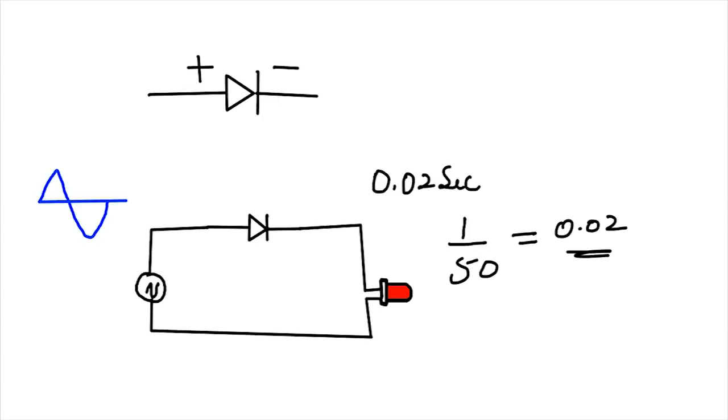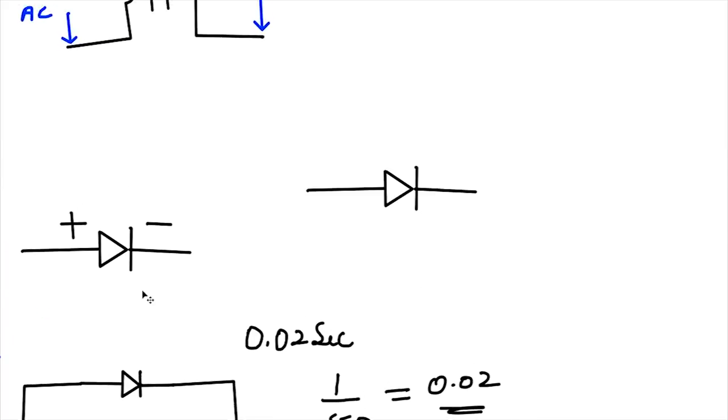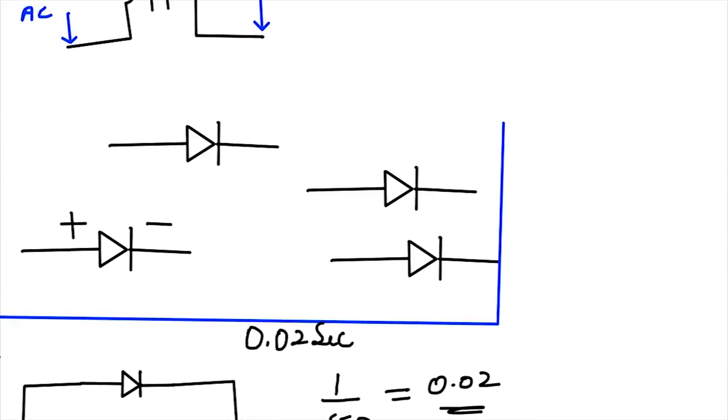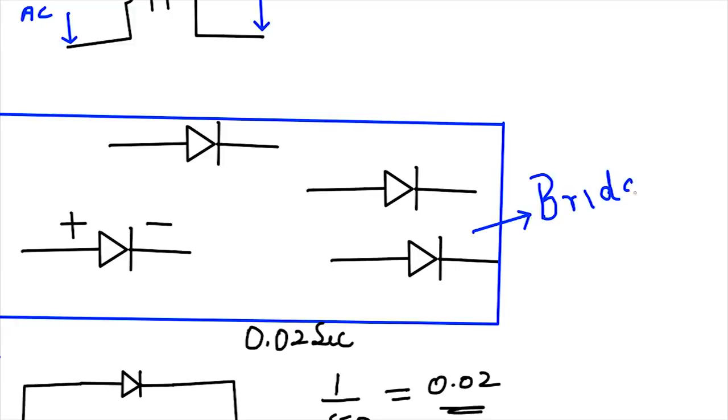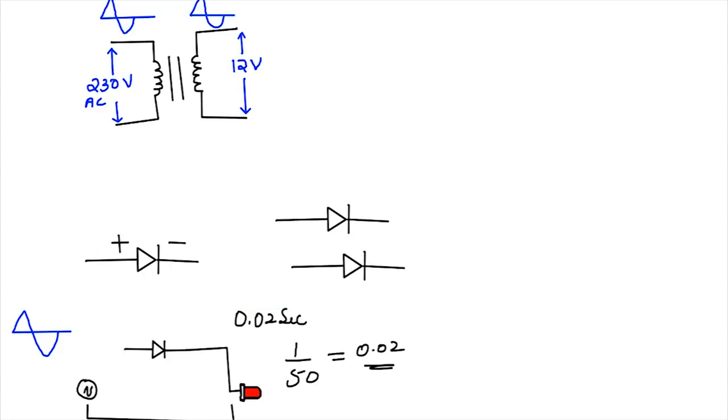To get an output which has voltage in both positive as well as negative cycle, we need to have not one but 4 such diodes in a proper sequence. I guess for few this may ring a bell. A combination of 4 diodes is mostly used in a bridge rectifier. Now the question is, how do I combine it to form a bridge rectifier?